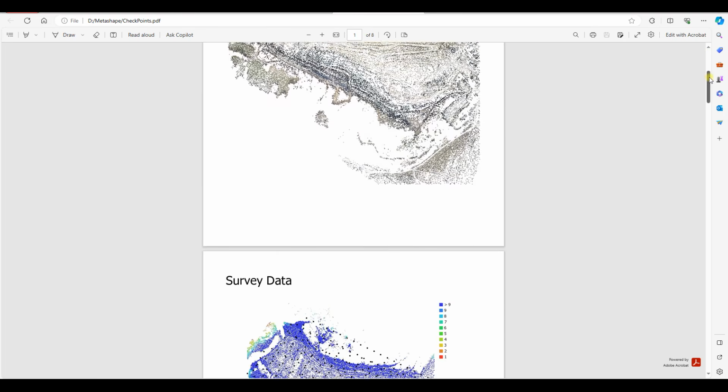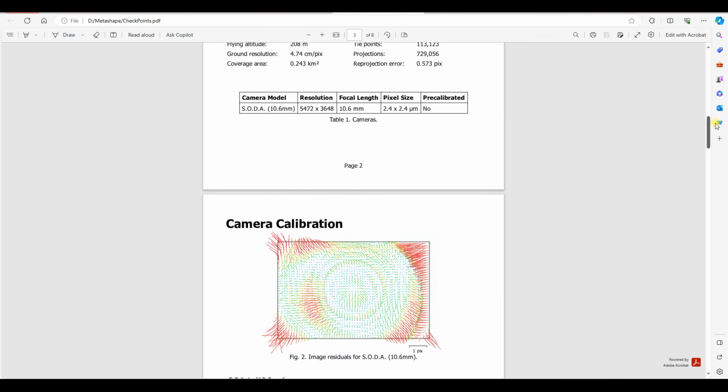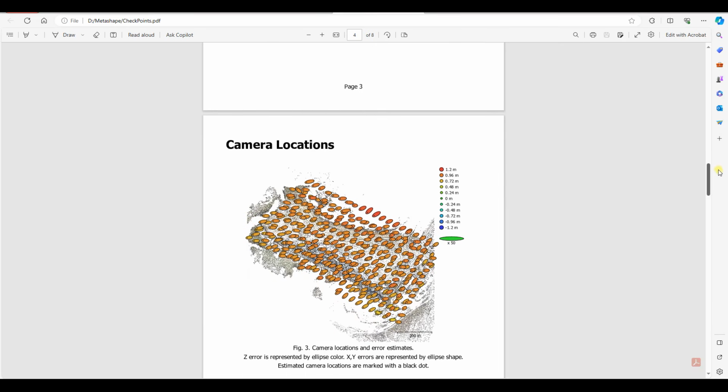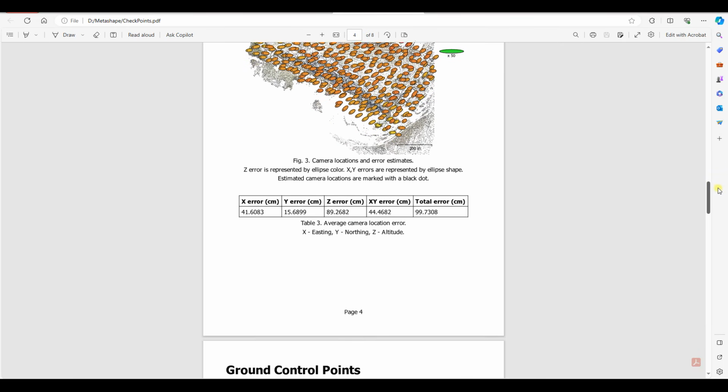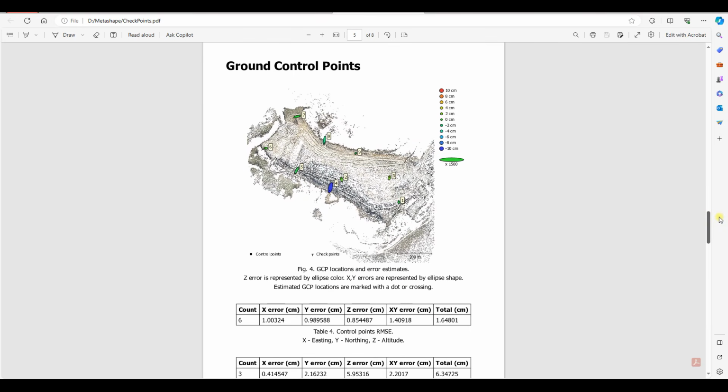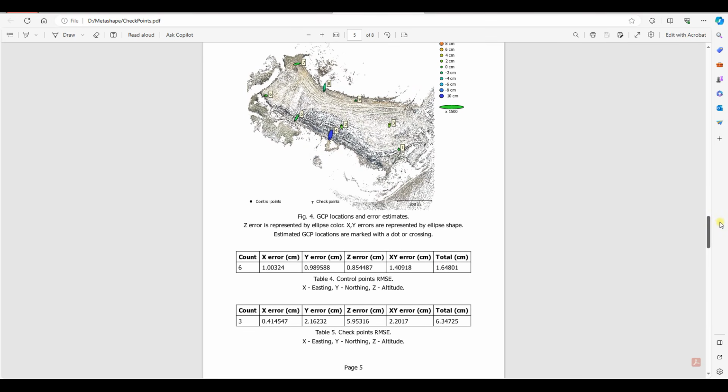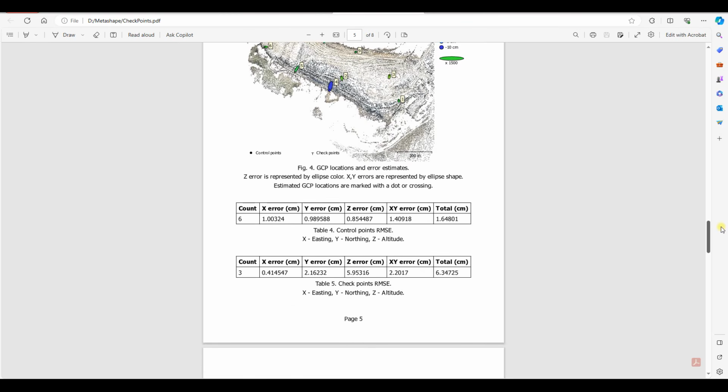Now your report has far more meaning, because we're not just showing how closely we have aligned the images to a set of points, but we're actually able now to speak to the accuracy of the data in between all of those control points. So 6 centimeters that we see here on our checkpoints, far more realistic value for your data set as a whole.